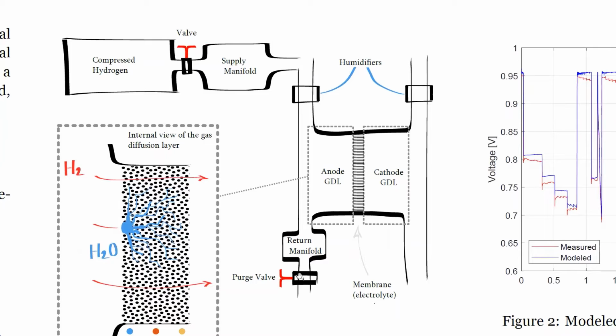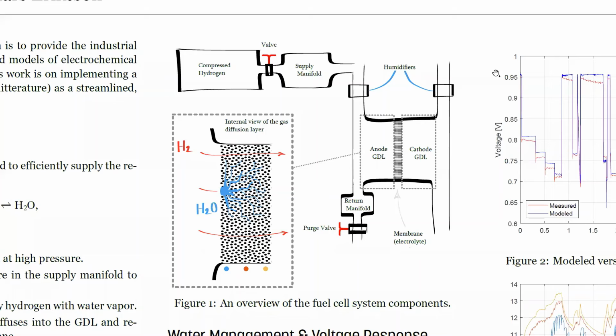And then here we have a purge valve, which is normally closed. So this produces a restriction here. And so eventually we might get too much water in the gas diffusion layer. And at that point, we can open the purge valve to discharge the water, but also, unfortunately, some hydrogen. So that was the anode side.